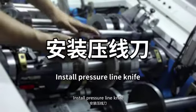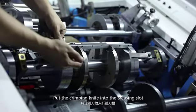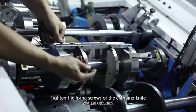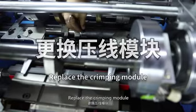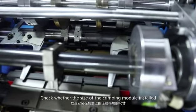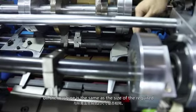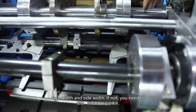Install the pressure line knife. Put the crimping knife into the creasing slot. Tighten the fixing screws of the crimping knife. Replace the crimping module. Check whether the size of the crimping module installed on the machine is the same as the size of the required face width and side width.